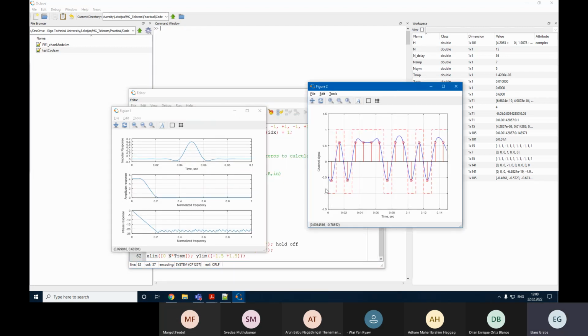So now you can see clearly rectangular pulse original, then middle value after converting into samples, and then the blue line, how this will look like after the passing through our channel. So as you can see, these pulses are no longer rectangular. However, if we just sample these values as we did for the rectangular ones, we will be fine and everything will work correctly. Yes, so that's very important that everything works fine.